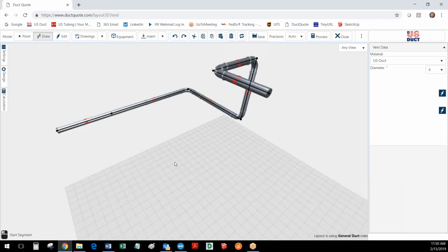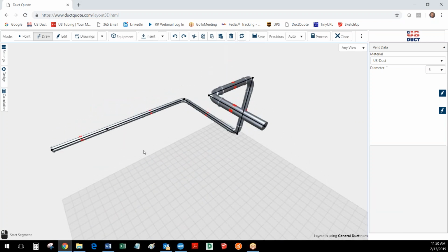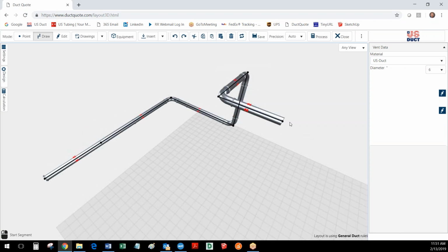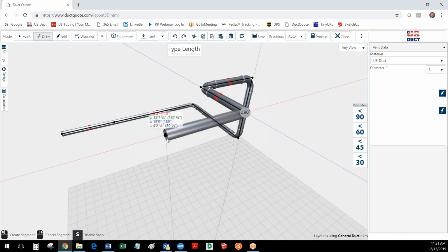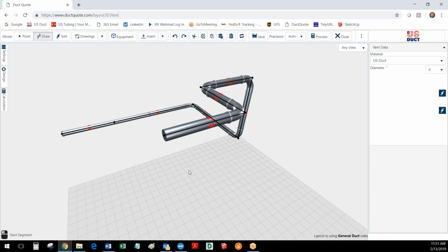All right. So one other thing, if I needed to make a branch, I could make a branch here because I now have a starting point in the middle. We're going to talk about branches a little bit more later on, but as you can see, starting or stopping a section is very simple. You start by clicking once, and then you move your cursor along one of the guidelines. Clicking a second time or pressing the Enter key is what ends the drawing of that section.